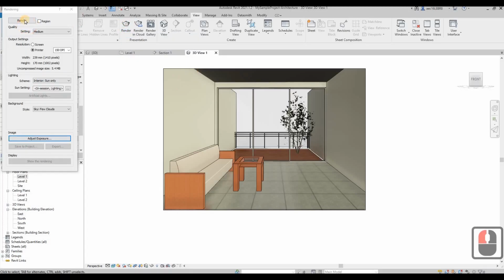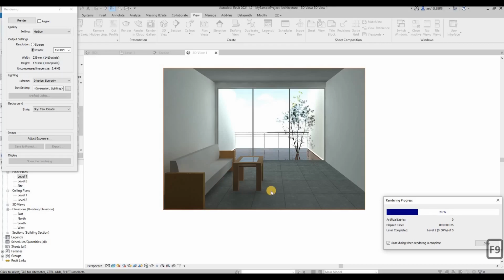Then you click on render again, render, and now you can see your tiles lines over here. Okay, it looks more realistic. Of course, if you want to improve the quality of your works, then you need to add some skirtings. You add a curtain palette. That's up to you to decide. Okay, so the plants look real, but it's missing the pots. You can always model pots here, and then the plant to sit on the pots.